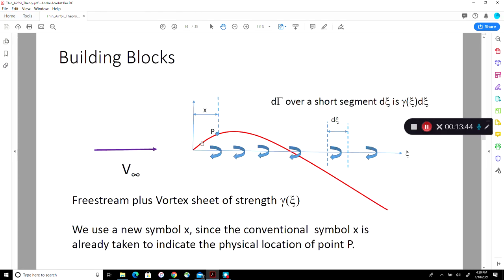But that's not convenient because the camber line has got some funky shape. So it's very hard to analytically integrate anything along an arbitrary shape. Then we say, okay, this is only 2% or 3% above the chord line. So rather than putting the vortex at point P or point Q anywhere on this red line, I'm just going to put it immediately underneath it along the chord line. So this gamma dxc is not placed on the red line, but is placed along the chord line.